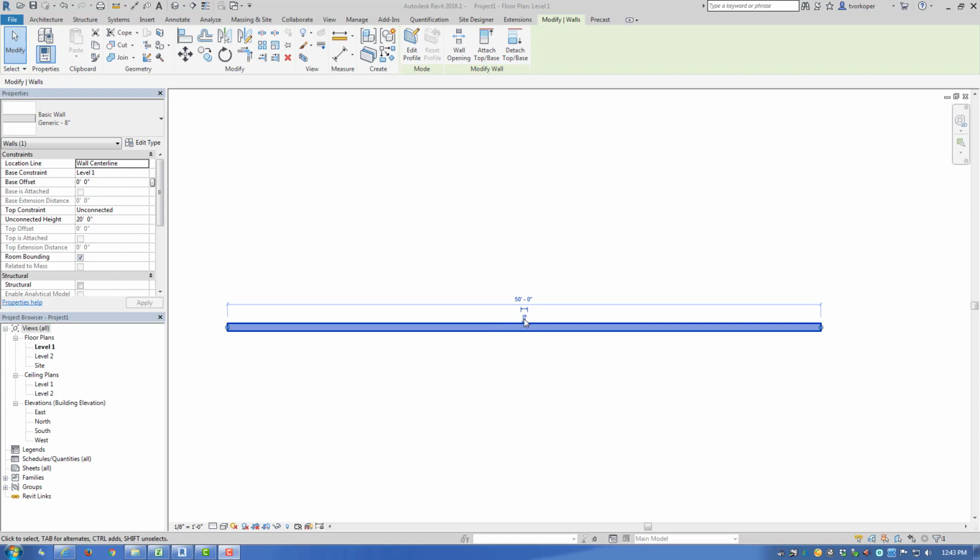If we click those arrows, the wall flips and now the brick is on the inside. And you can see as I go back and forth that it is flipping around the center line. Let's take a look at why. If you take a look at the properties palette of this wall, again, the wall is highlighted, so all of this information is talking about this wall.